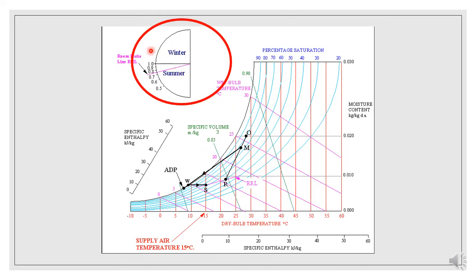Right, this is another example whereby you can use this sensible heat factor, and again after some calculation, when you know the sensible heat factor for the room, for example here it is 0.75, just draw a line and transfer this line to the room condition point. So here we call it the room ratio line, so you can actually call it RSHF.